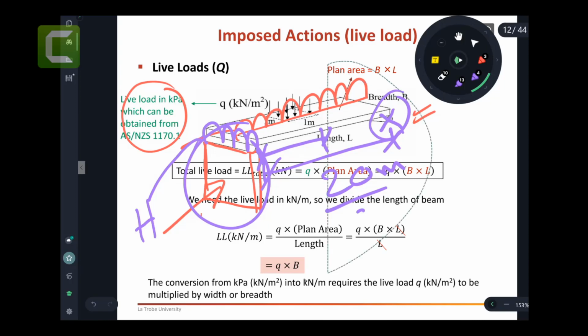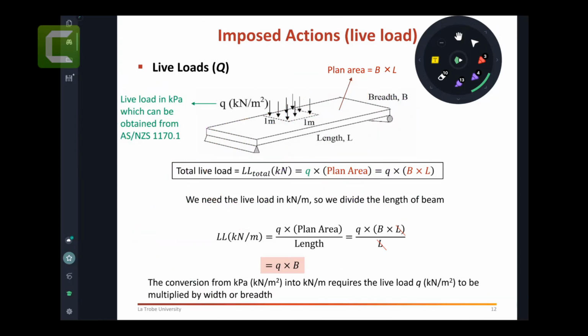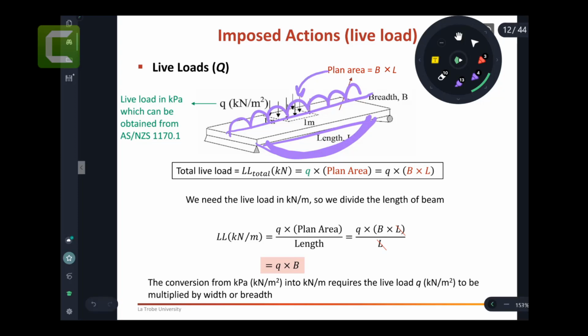Okay. So as I said to you, in this worked example, their interest was about finding the line load that they will end up using to find how we are stressing the floor of the bridge. Remember the bending moment diagram, shear force diagram? These will come from finding this purple line load. To find this purple line load, we have to multiply the pressure by B, which will change the pressure into line load.